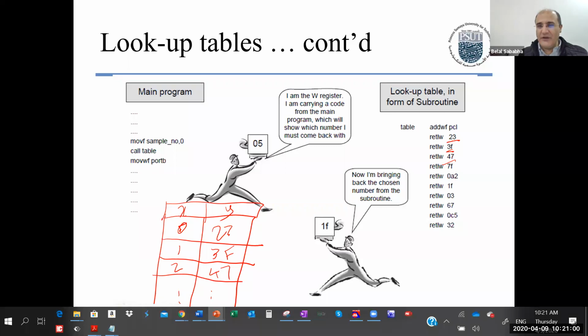Well, thank you, good question. You need to think deeper. So this is, you return one value. If you want to return 2 values, you may want to think of moving the values to a memory location tied to what you sent, right? So when you call the table, you say move literal to W to a memory location F. That's that you add W, right, to indirect addressing mode, maybe FSR, and you go store it in a memory location and the memory location after it if you want several values.